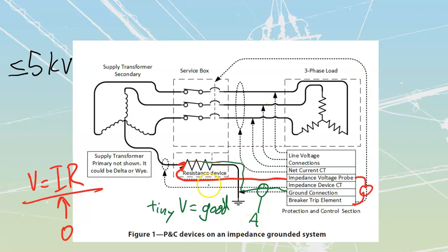And the reason for this is because we are required to know if we lose continuity on our resistance device. If this device would go open, obviously, we would not be able to complete this path back through. This ammeter would register 0, and this voltmeter over here would also register 0. It's not going to be able to read anything because we cannot drop any voltage across it.